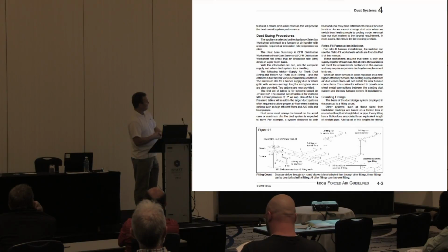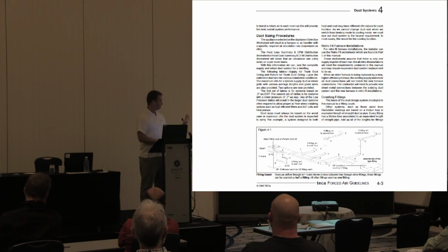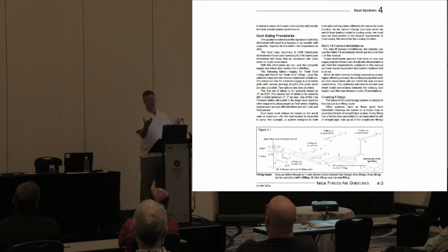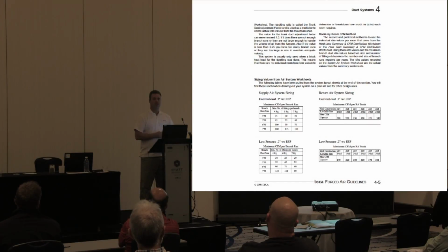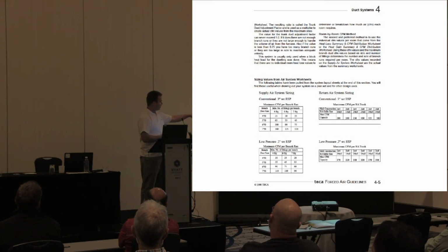That's right. So basically, I'll go over the duct design and the way we do it. The picture's a little crappy, but basically what we do is we count fittings, and instead of getting equivalent length, we get a sense of how far away it is from the furnace. So we're able to account for the fact that a duct that goes all the way upstairs will have less air than the same duct that just goes straight onto the main floor or into the basement. You're going to have to upsize that vent going up there if you want to get the amount of air that you've calculated in your room-by-room heat loss. So these forms here are what they go through.